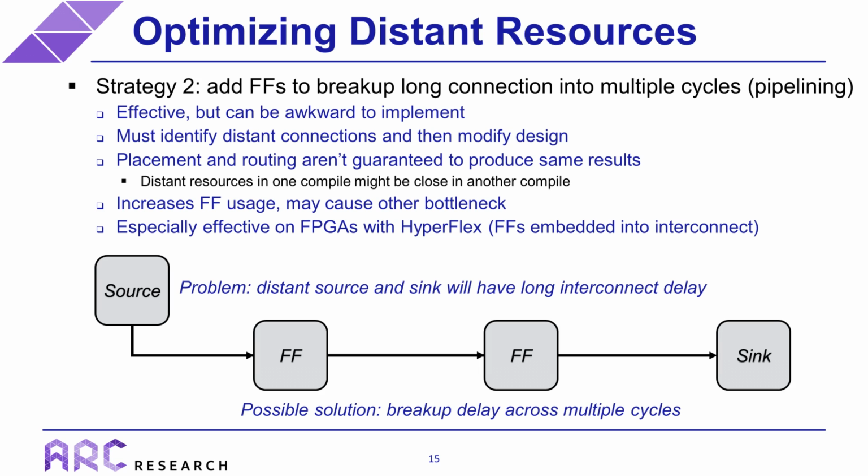So, you could add registers only to find that another path is now longer on the next compilation. For a huge design, you could potentially iterate numerous times, adding registers to different wires with a bottleneck just shifting every time you compile. In addition, another potential challenge is that this pipelining increases flip-flop usage. In general, increased flip-flops tend to greatly help reduce delays, but above some threshold, some extra amount of registers can actually create new bottlenecks from increased routing congestion.